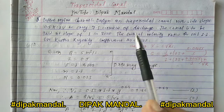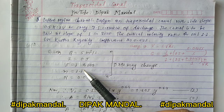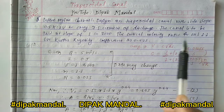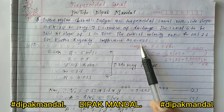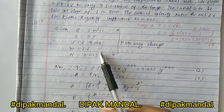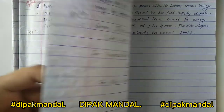The canal is to be laid at a slope of 1 in 3000, and the slope of canal is given 1 is to 3000, and the critical velocity ratio for the soil is taken 1.1. And use Kutter's rugosity coefficient as 0.023. So all these parameters are given in the question. Now we have to design the trapezoidal canal, and before this video we already designed one, I will show you here.